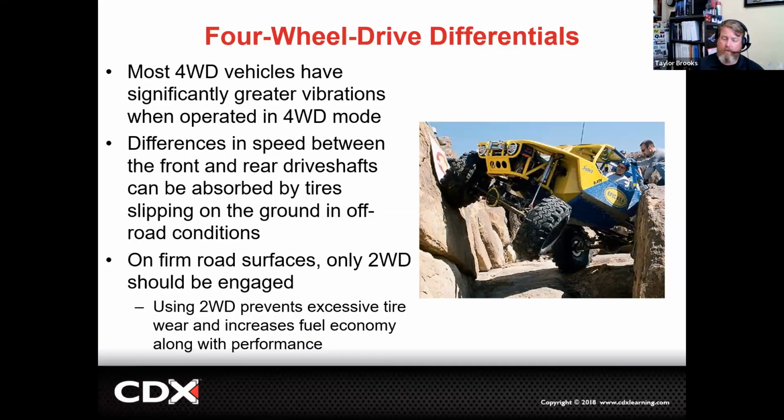If we start to drive at speed in four-wheel drive, we will get a very aggressive vibration through the chassis. We will also be able to put a lot more strain on the components. The driveline components wear out faster and tires will wear out faster.